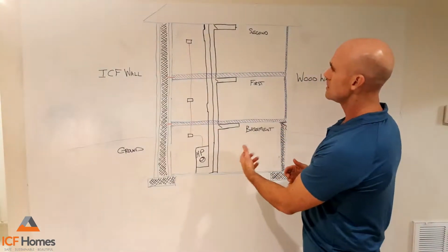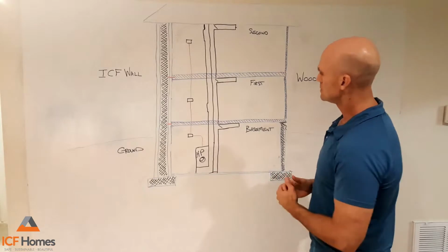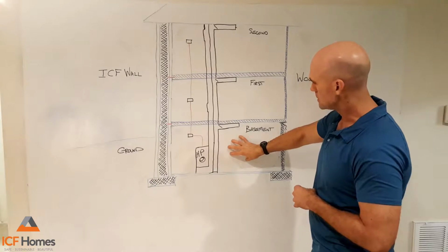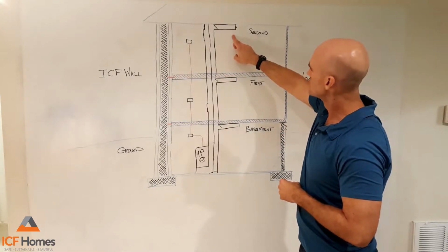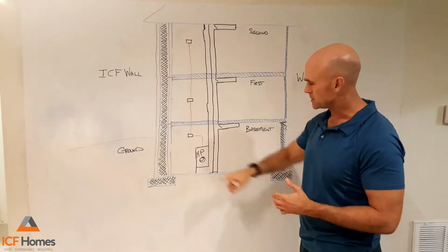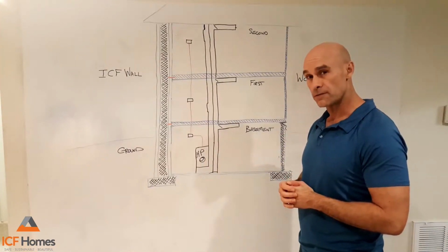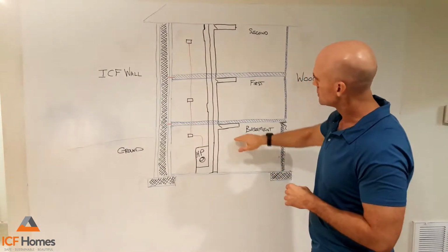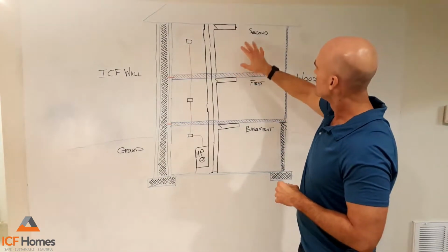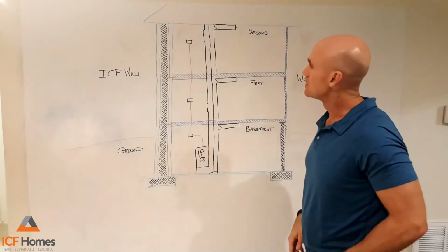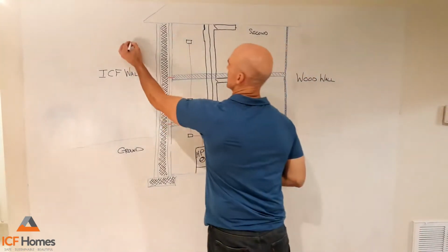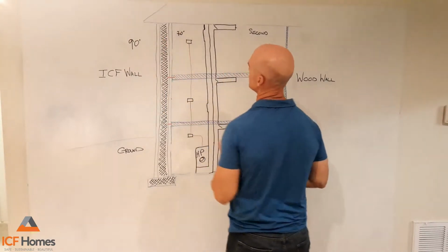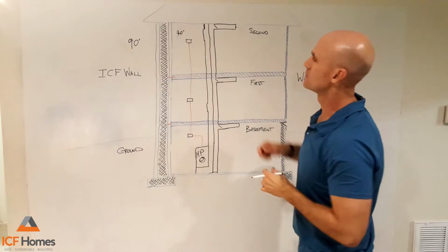But one of the really neat features about good HVAC design is to use our steady basement temperature and get that steady basement temperature all the way up to the second floor of the house. Because all the energy that requires is just the fan of the heat pump itself to move the air from the basement all the way up. And the way we do that is a zone system. So for example, if the second level of the house in the summertime, we've got a 90-degree day outside, and we're trying to maintain 70 degrees inside, it's going to heat up on the second floor of the house.